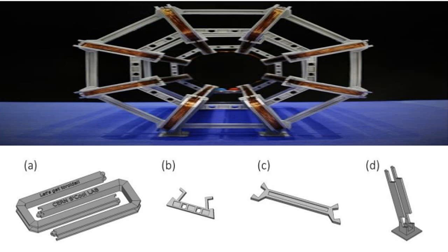between them. To connect the 8 coils, we designed 2 different pieces, an inner strut and an outer strut. 8 inner struts are necessary to make one complete inner ring, while 8 outer struts make up an outer one. These struts were designed with hollow surfaces and holes in order to both resemble the real detector as well as to use less printing material while keeping the structural support.